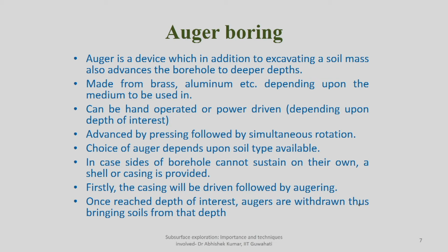So please remember, this is only for advancing the borehole, because whatever kind of soil you will be encountering in the majority of the boring methods, it's mostly minimal to highly disturbed soil. So you cannot actually use it for strength characteristics, but it is to proceed to deeper depth. If you are going for a 20-meter borehole, and if you start collecting soil samples continuously, it will take a lot of time, and it may be possible the soil layers are not varying that significantly or that frequently. So even one sample will be able to serve your purpose, rather than going for continuous and multiple sampling in each soil layer. So that's why we go for sampling, and we go for boring.